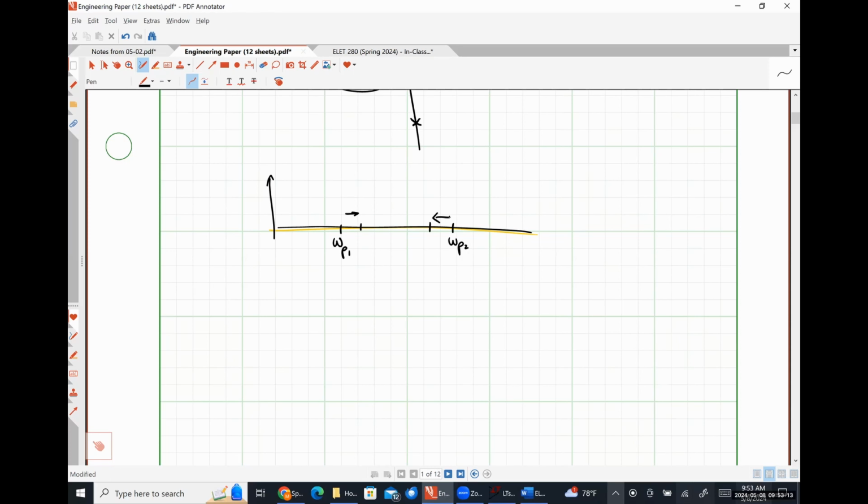In the common gate amplifier, which I just put the homework assignment for up earlier today, I haven't done the small signal look at it, but I think that CSB will not be 0 because the source isn't at ground.